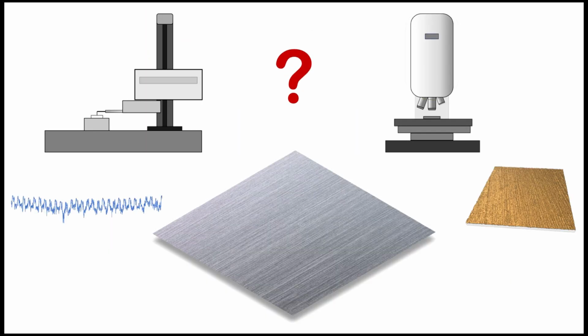All these possibilities leave a lot of possible options to users. Therefore, some of them face an important question. When is a profile measurement enough? And when is a 3D aerial analysis required? Three-dimensional metrology is not necessarily better than 2D profilometry. It depends on the context, the surface complexity, and the instrument available. Each instrument has its strengths and limitations. It must be used in the right context.